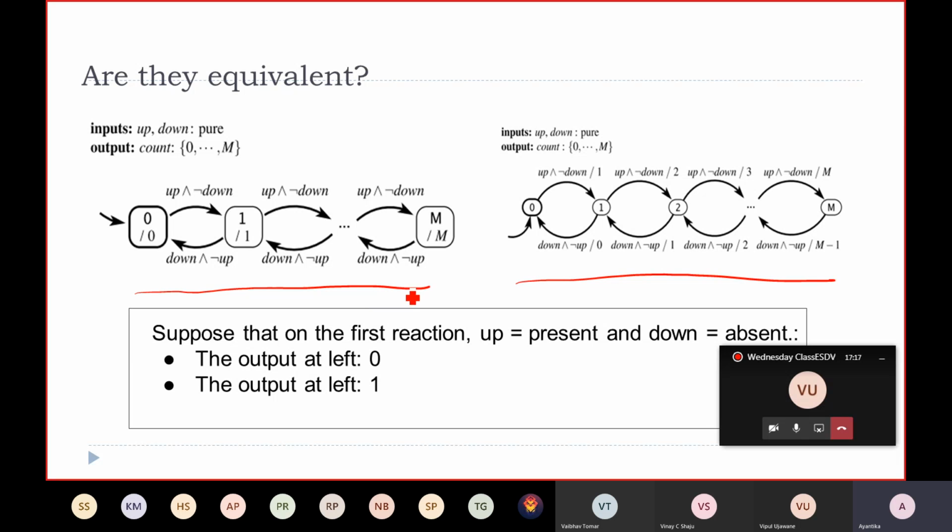These are direct FSMs where you have just considered states according to the number of cars, or number of vacant places, the number of counts practically. And this is the Moore approach and this is the Mealy approach. So what is the difference? Just observe this. According to the definition of the Moore machine, we have stated that we will be taking the output from the current state.